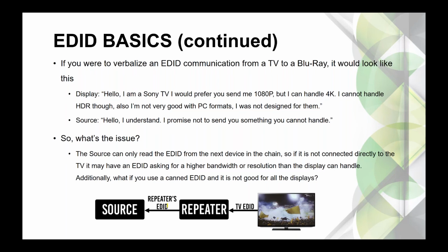we hope it works. We hope the repeater is doing the same thing. We hope the repeater is just passing the EDID through intact. However, this doesn't happen, because repeaters, like AVRs, do this differently. They can even pass information that they think may enhance the signal, i.e. scale the signal. So the repeater is doing different things, and ultimately there's a breakdown in communication. And sometimes there's more than one repeater, in a more complex system with more display locations, more endpoints. So this is where it breaks down.